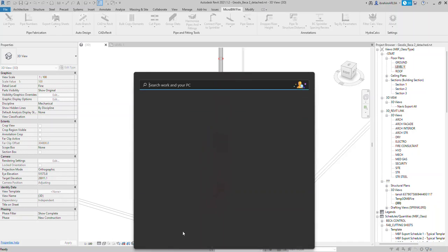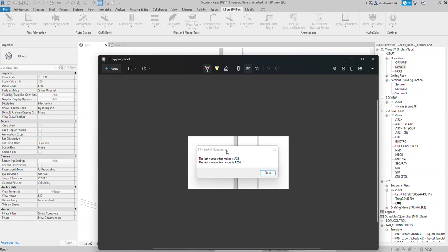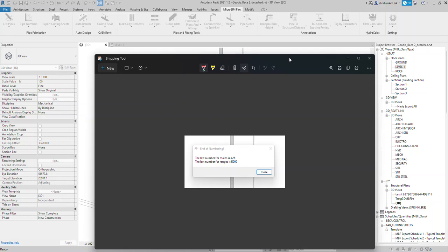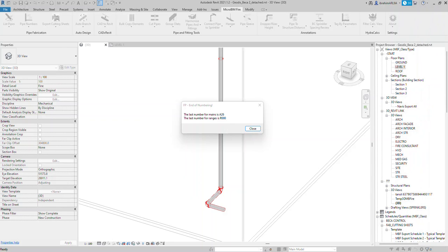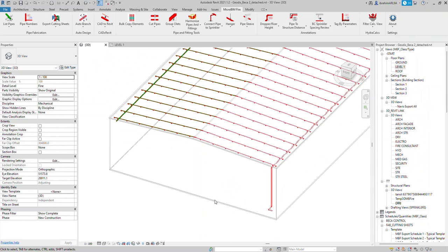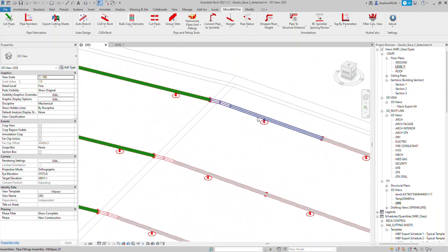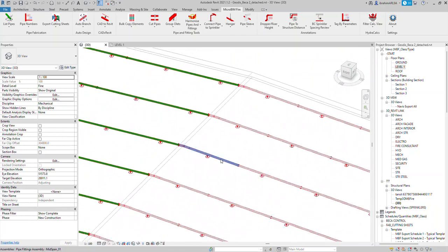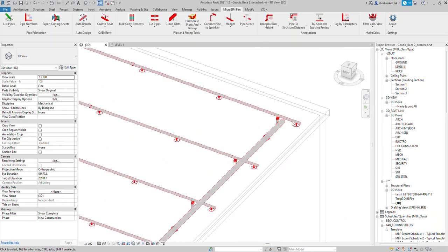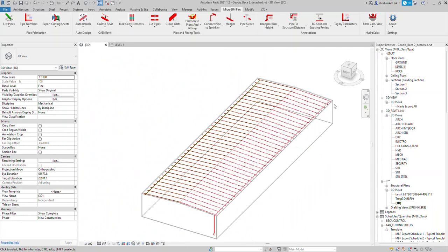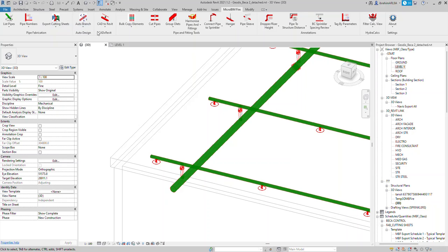So take a screenshot of what we get here, the maximum is 826. Just take it in here, and then you can continue from the other half. A very basic visual review will help you understand what pipes are numbered and what pipes are left if not numbered, but it seems here everything is numbered correctly. Now let's go with the numbering for the other half.